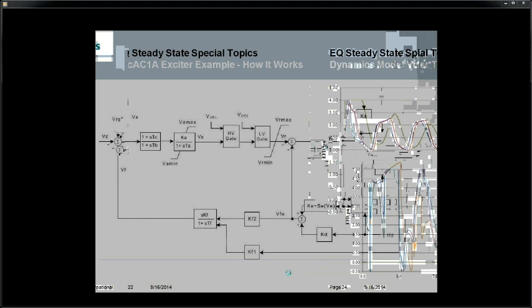Most of the equipment attributes and whatnot are contained up in the 61970 standard. We also have classes added here, to define the individual phases of an AC line segment, switches, energy consumers, and so forth. So we basically duplicated the three-phase balanced model with an individual phase model,